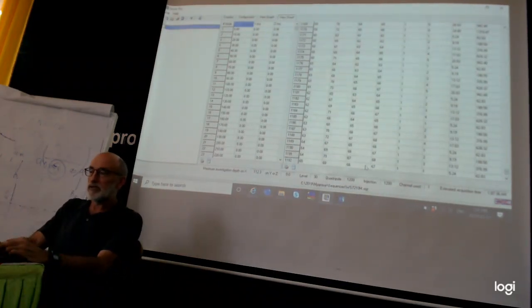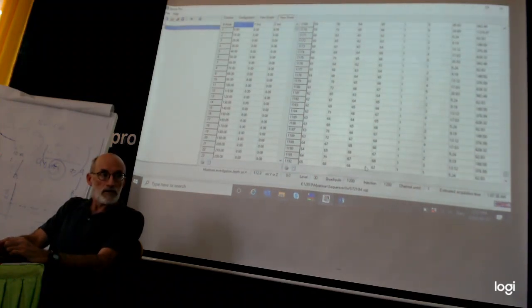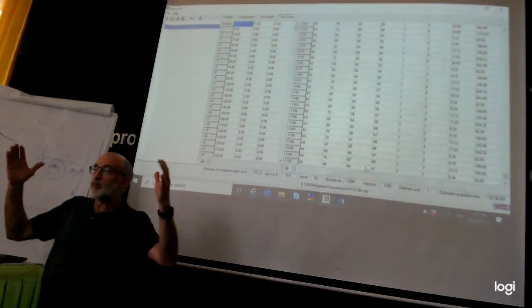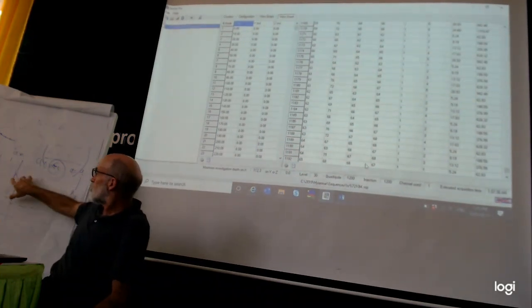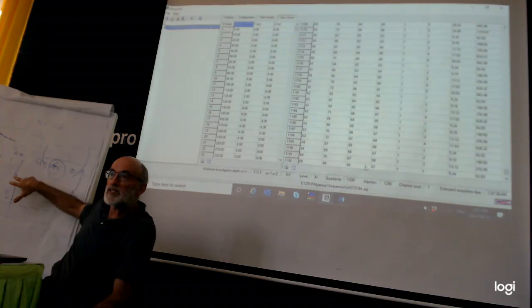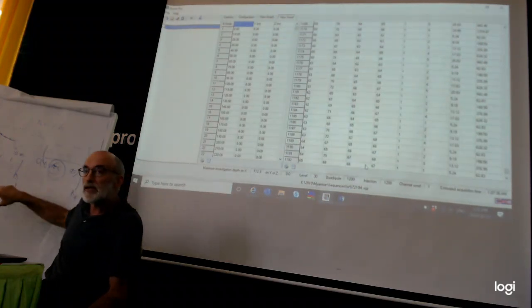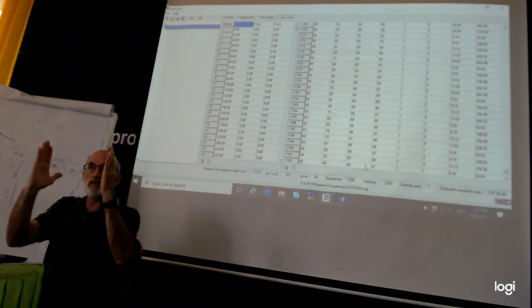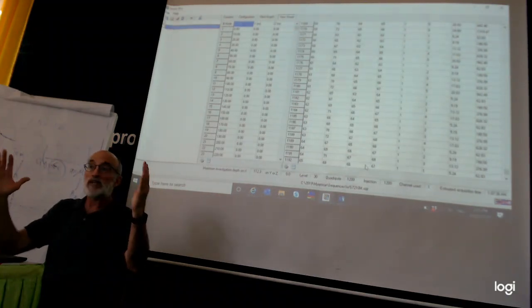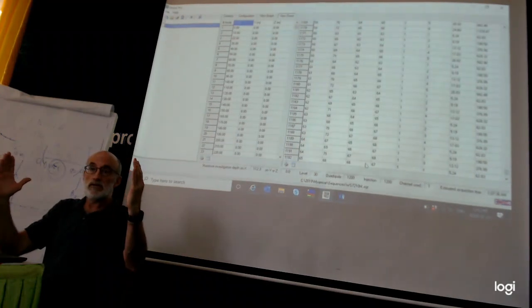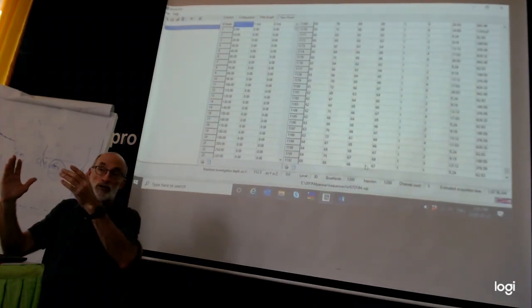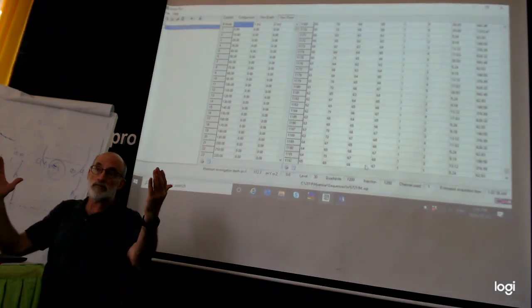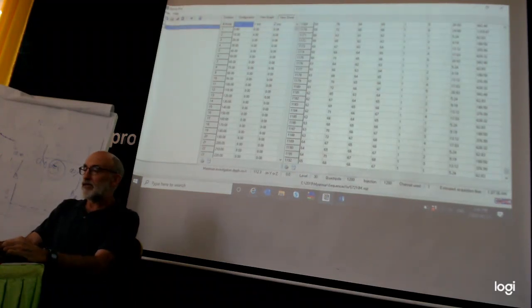So the electrodes A B and M N. So we've got our A and B electrodes, but we're always just 10 meters apart, one spacing apart on our MN. If we expanded our MN to be 20 meters, we might get twice the potential voltage. So we'd go from 2 millivolts to 4 millivolts.